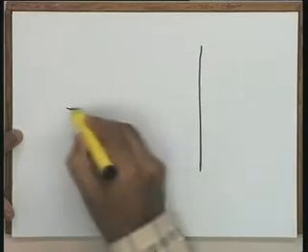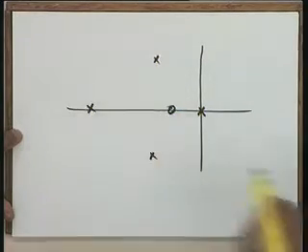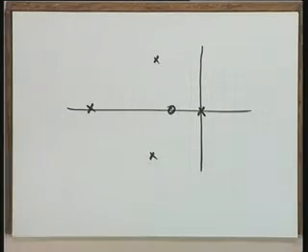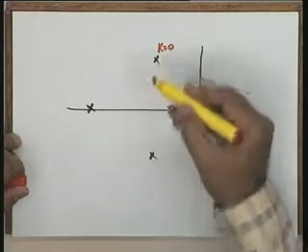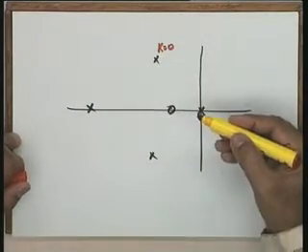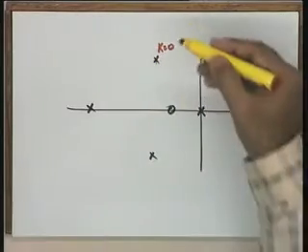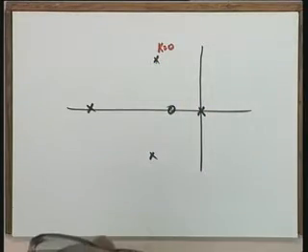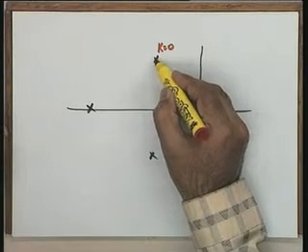In general, let me take a general situation, so that the specific situation is avoided. This is a complex pair. Here is a pole, here is a zero, another pole. In this particular case, now there is no circle business. You cannot say in general that the locus leaving this particular point is a circle. Now what you need is that a root locus will start from k equal to 0. I really do not know which direction it will go. I want the direction of takeoff from this particular point. It could be any of the directions as far as the total 360 degrees angle is concerned. And now the direction, suppose it is phi p. How do I determine, how do I write this phi p?